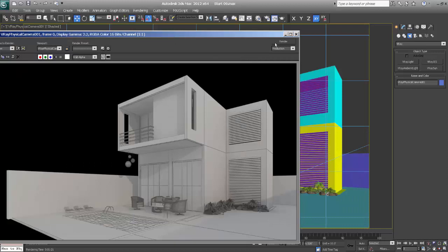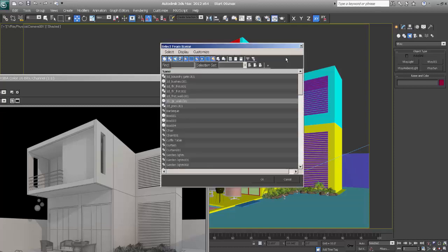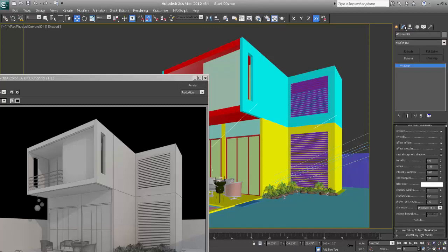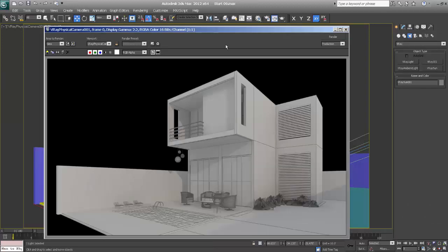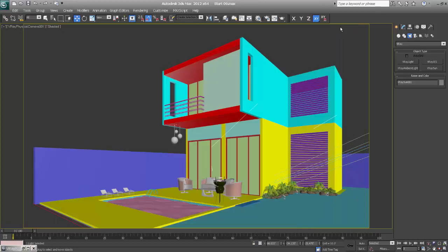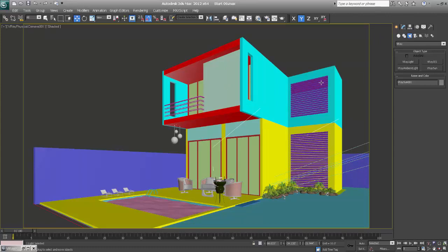the light. Because we want to show the evening scene, I'll press H. Select sun. Set turbidity to 5, and the shadow subdivision will be 5. And the last small change I need is that the sun will be pointing slightly downwards, so it will give more of a sunset feeling to it, and this is how we can go forward.